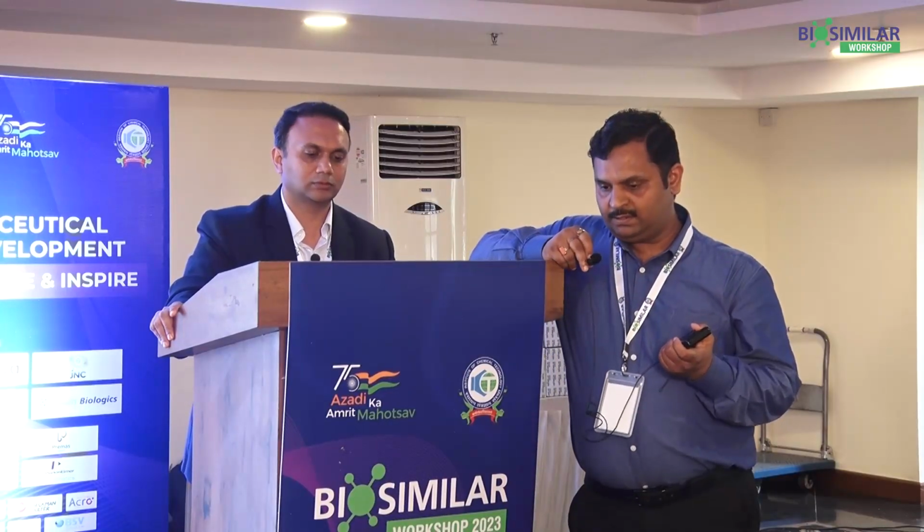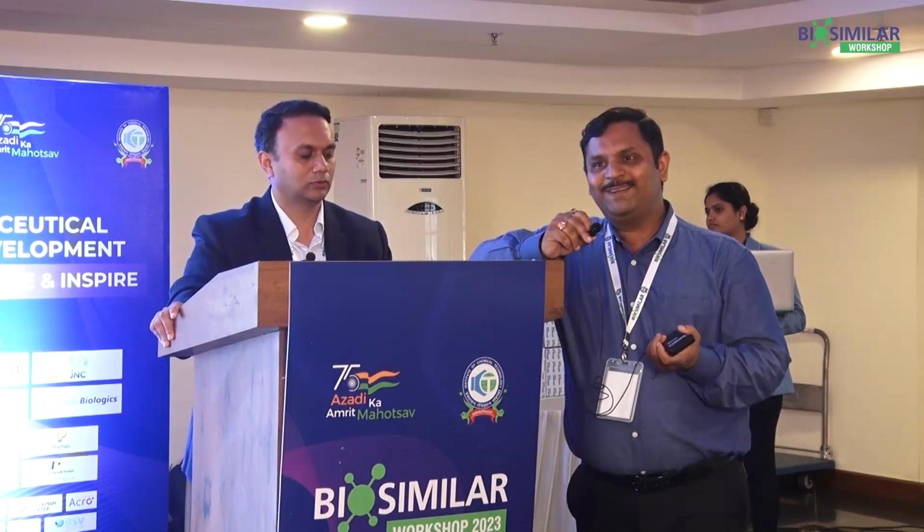Can I suggest one thing: in commercial manufacturing, especially in linear gradient, we collect a peak. The peak starts within the gradient, and we have a collection parameter based on UV. I will say that is more important than the elution factor. Definitely there will be an elution factor difference of, you can say, 10% maximum. I don't think anybody considers above that, so it is not a big problem as such.